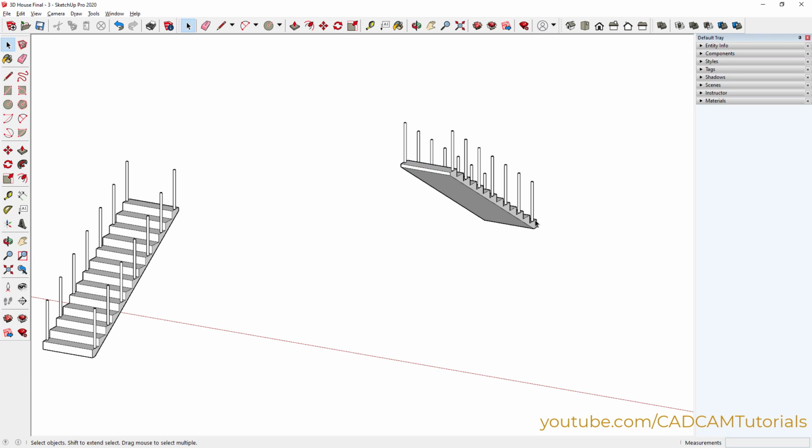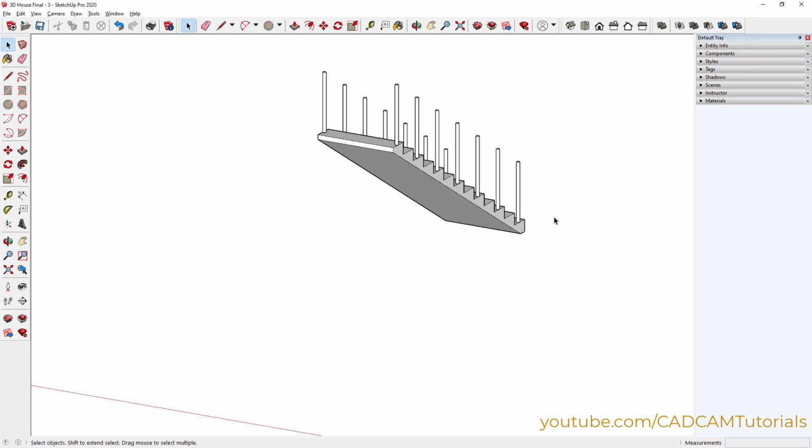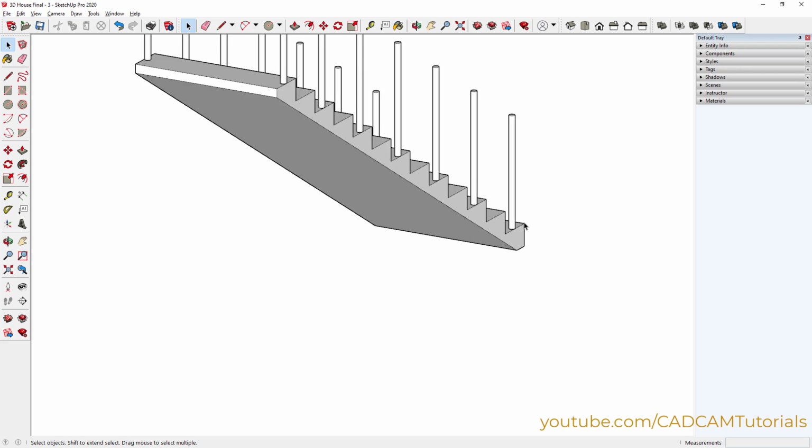So this opposite side is ready, but on this opposite side we will need 12 steps because we want total 25. So these are 13, these are 13, we want 13 plus 12. That means we will have to cut one step. Suppose we will cut this bottom step.